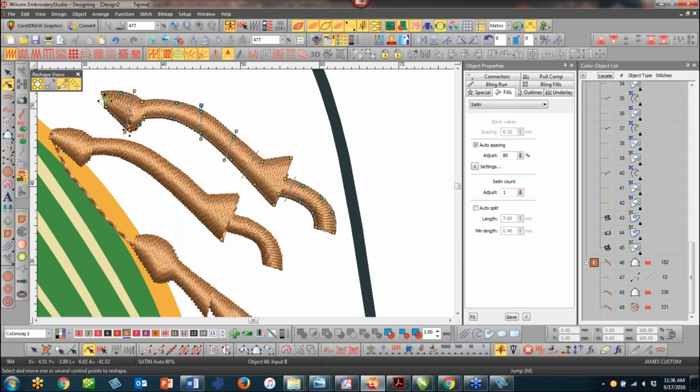If I go in and do another one here, if you want to delete them, you just click on the little node point here, left click it, and press delete, like this. Left click, press delete, just like that. So you can get rid of them also. Again, these are the guide points used inside embroidery that allow you to control the stitch angle. And yes, it does give you a lot cleaner look with the object on the screen.